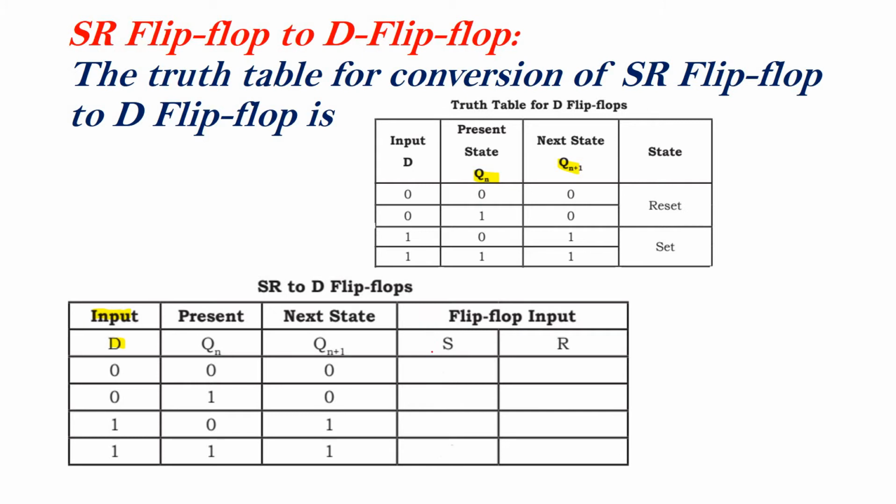So this is obtained from the excitation table of the SR flip-flop. How can we remember easily? Here, Qn equal to 0 and Qn plus 1 equal to 0. So S is equal to 0 and R is equal to X. Here both are equal to 1. So put X first and 0 next. Next 1, 0. I have to write in reverse order. Reverse order means 0, 1. Write in reverse order 1, 0. In this way, I have to fill the excitation table for the SR flip-flop.